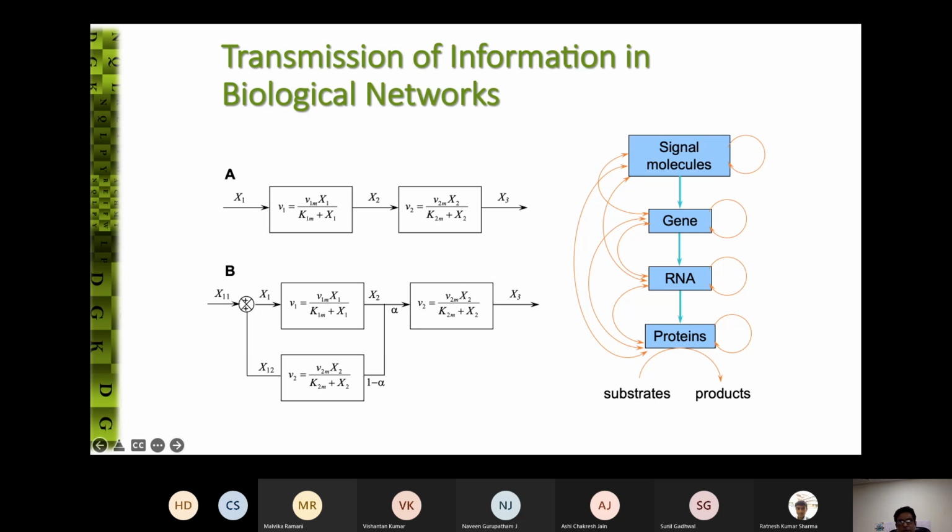That means forward divided by the loop, right? So in this direction, it will be the forward. If I were to write this as G1 and G2, then I'd say G1 G2 divided by the loop. Then I'll have to work out how much this is. There'll be G1 G3 by 1 plus G1 G3, and then a G2. So G1 G2 G3 divided by, and then you work out the entire loop, and that will give you how this works out. Depending on the sign, it will change. The signs at the bottom, right? Do you remember that part? How this happens? If not, just go back and see.